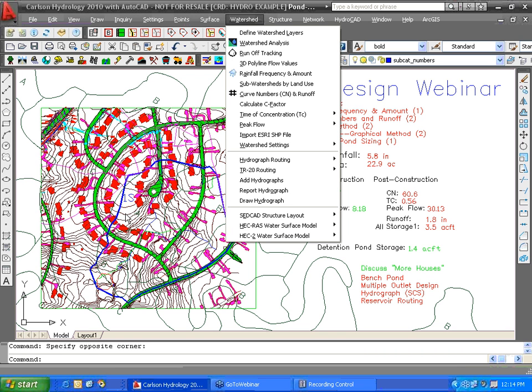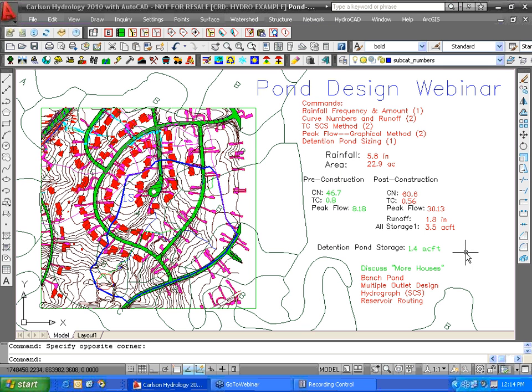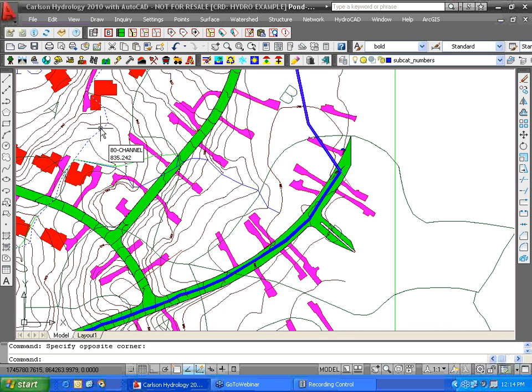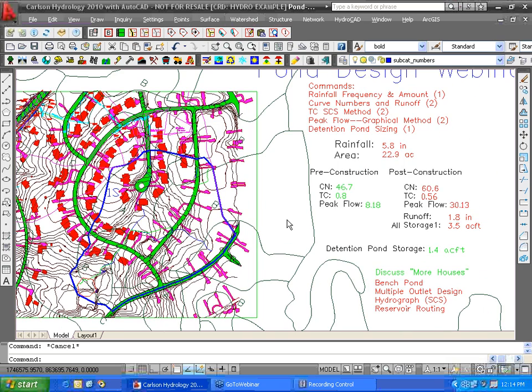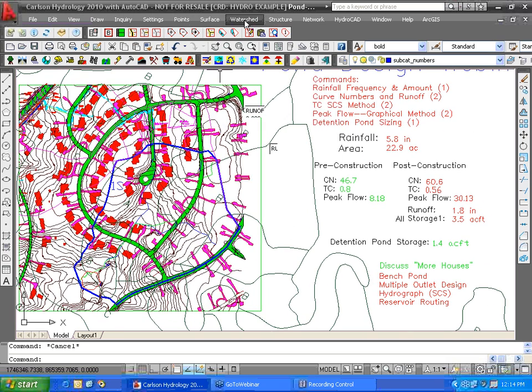And I should point out, when you make a TIN file of the surface, it is best when you have nothing but a contour map to work from, to draw high and low streams and ridge break lines yourself as 3D polylines. I have that particular stream break line. I have sort of a ridge break line over here, another stream break line, and they help draw the water in, to get a more accurate surface for the area involved.